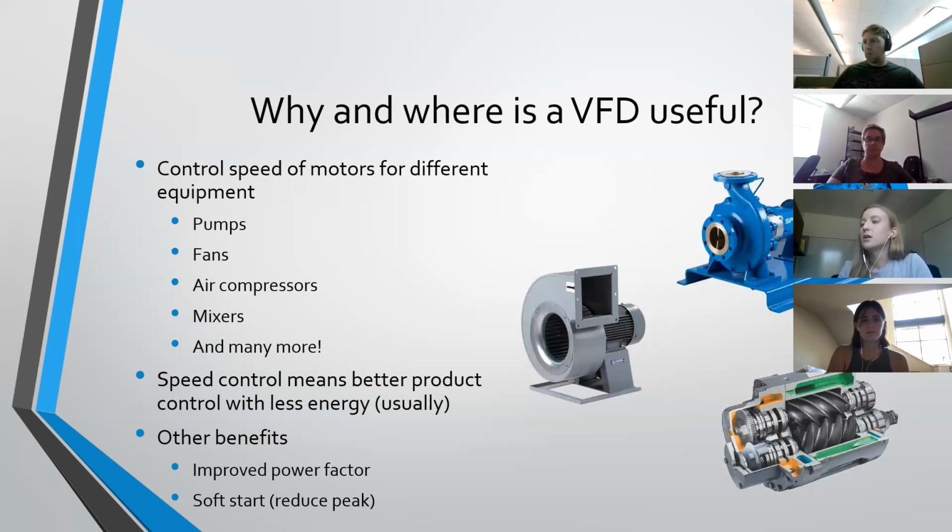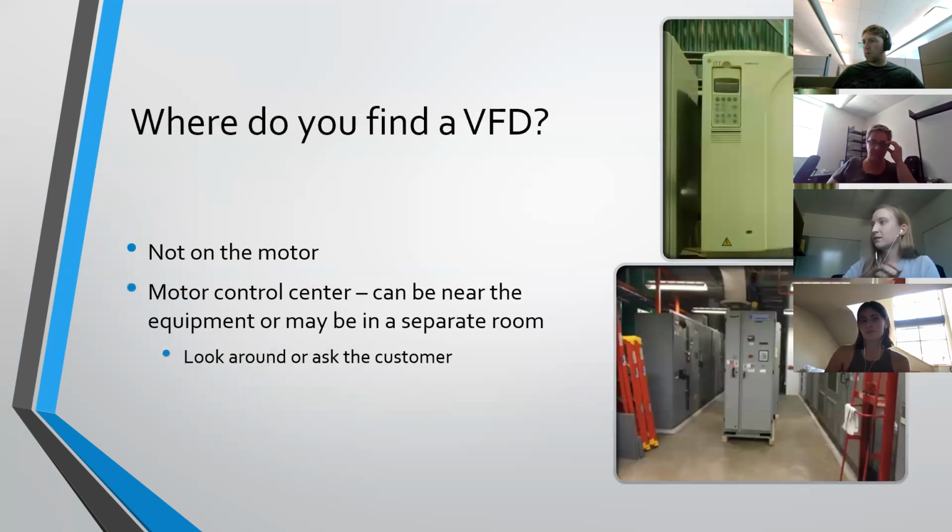And then soft start, VFDs can also be used as soft starts. So normally when you start a motor, you've got a huge inrush of current that spikes up your power consumption real quick. And a soft start means that you are slowly ramping up that current draw, and a VFD allows you to do that. So a couple extra benefits.